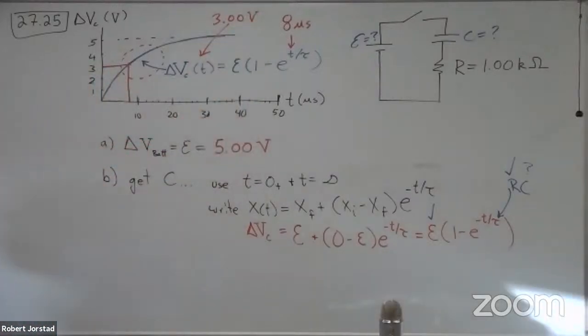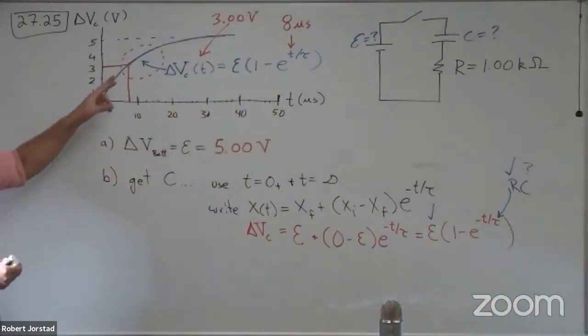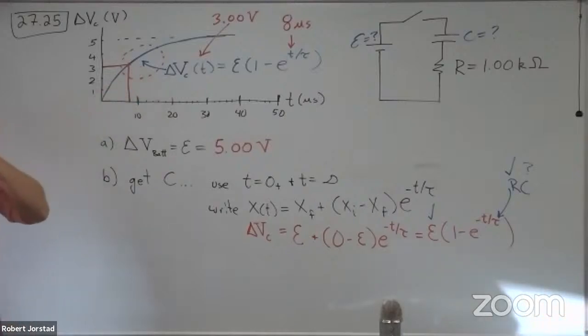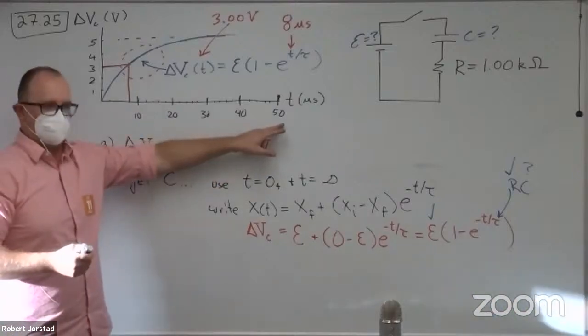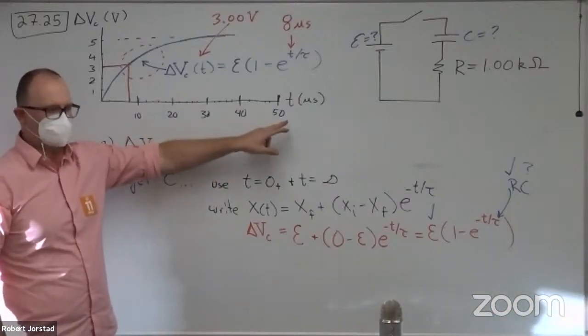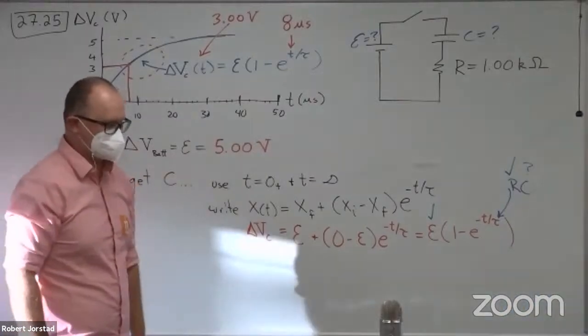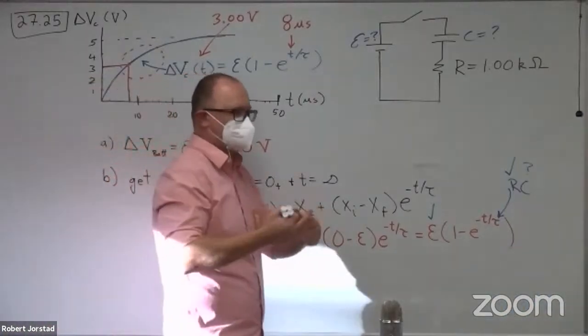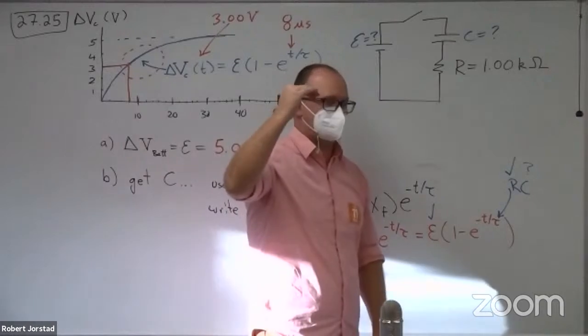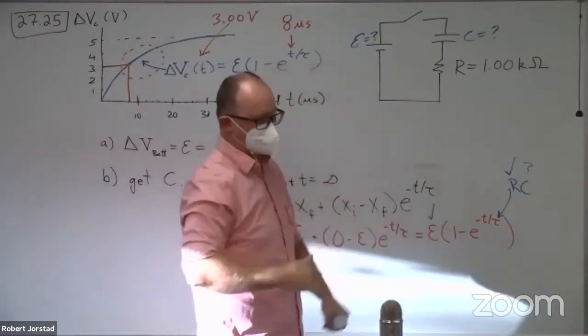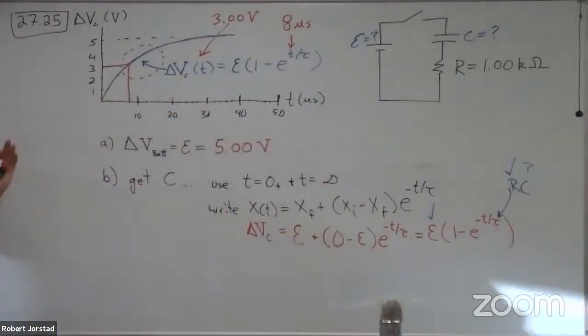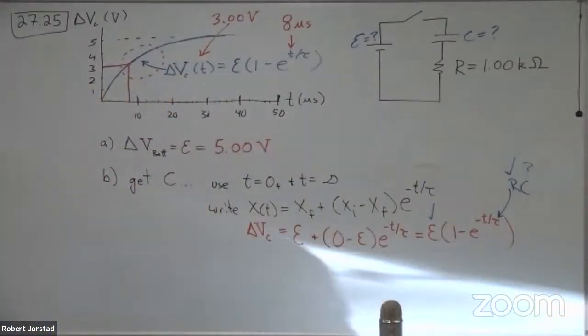The thing that students forget is you got to pick a time somewhere in the middle. Does that make sense? People love to say, oh, 5 tau is 50 on this plot. And it turns out, I don't think that's right. I don't think 5 tau happens to be 50. It just kind of looks like it. But you can't tell whether it's at 0.97 or 0.98 or 0.99. And so you could actually introduce a huge error there. So far, so good?